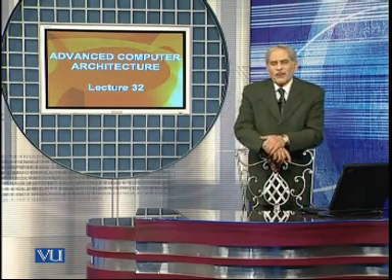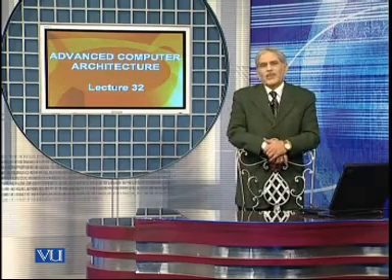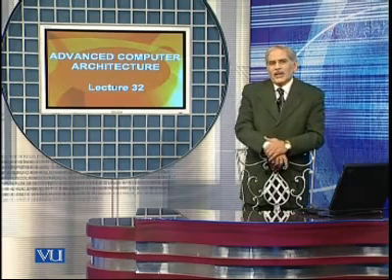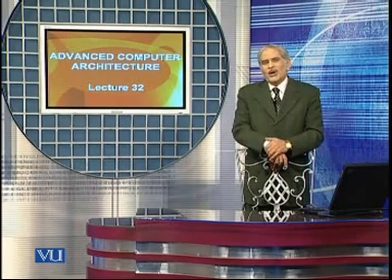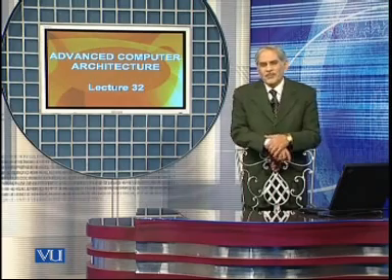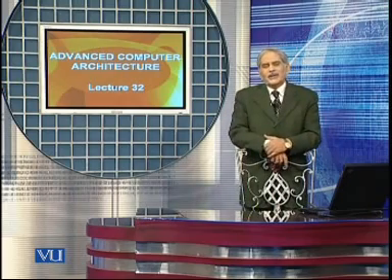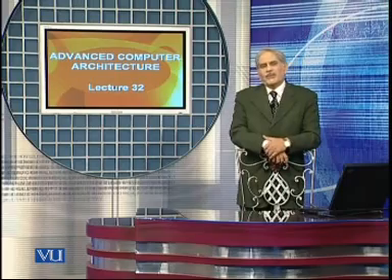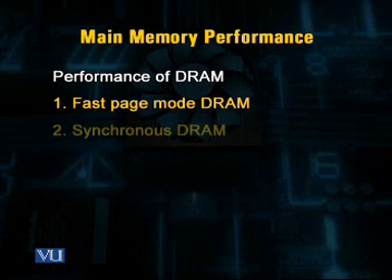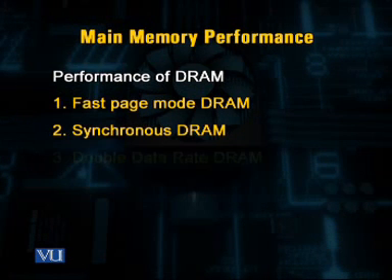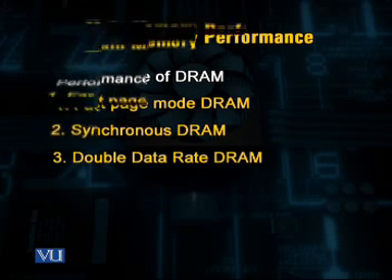The performance of a dynamic RAM chip has always been important for the system designer, as a system designer likes to use fewer chips per system. As a result, several improvements have been made to the design of the main memory. These improved designs are fast page mode DRAM, synchronous DRAM, and double data rate DRAM.